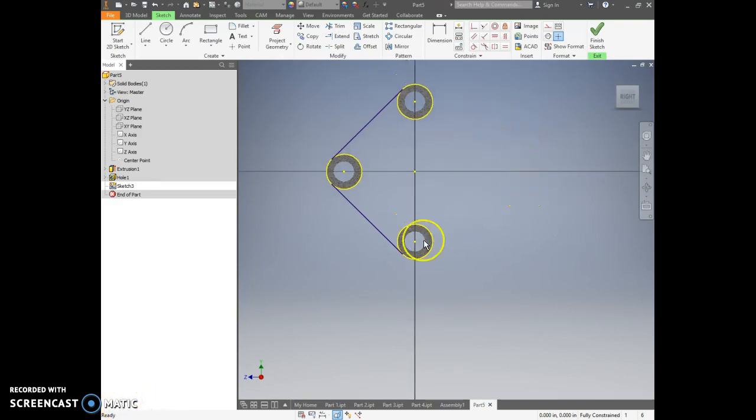So the next part of this out here is this circle, or this arc. I typically just draw it with a circle. So I typically draw my circle out there, like so. And once again, I use my tangent constraint to make those two tangent with each other, and those two tangent with each other. Once they're tangent there, I usually try to drag this to approximate size before I do anything else. But then I go ahead and just trim off what I don't need. So I make a tangent there, trim it off, so there I'm left with just my arc.